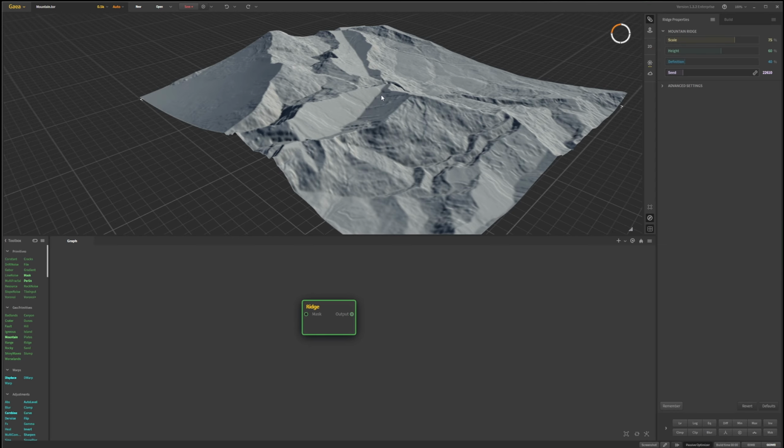You can adjust the rendering resolution of the 3D viewport for more detail. At the top toolbar, it currently reads 0.5K. Change it to 1K.